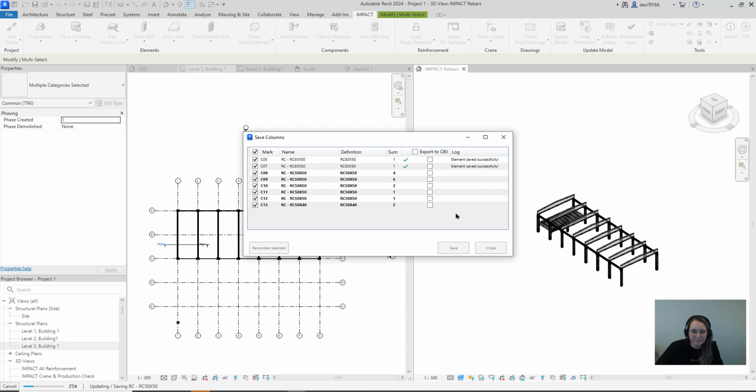We're saving them to the database and all the information about them: geometry, the components, casting materials, reinforcement, it's going to our database. That's what we're doing now, because once we have saved the element, we can preview it in our central tool, project manager, but we can also make a shop drawing out of it.